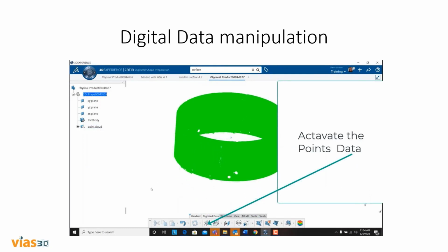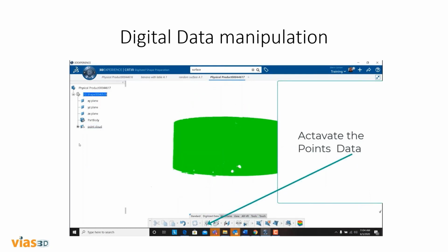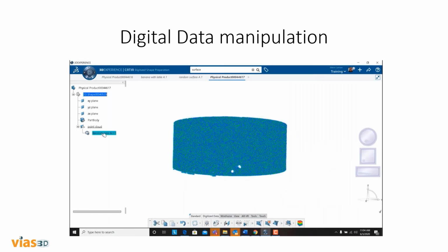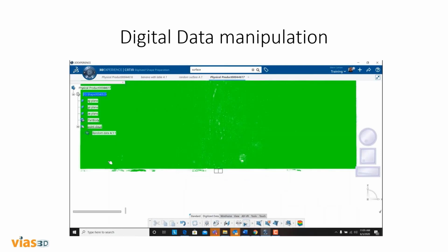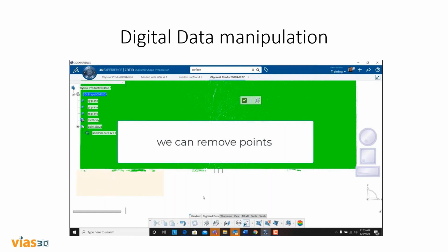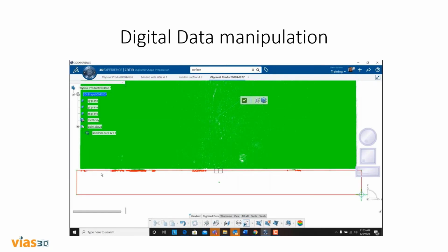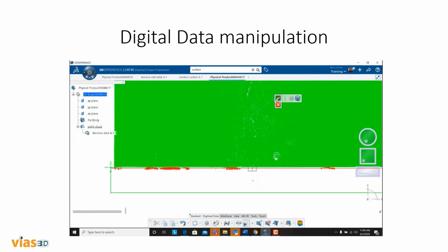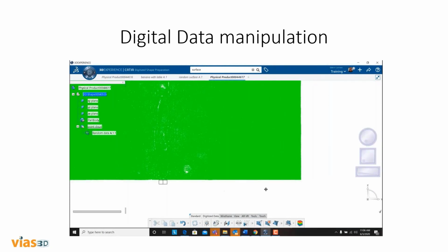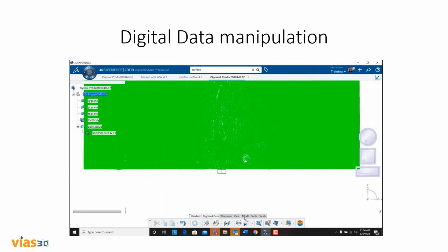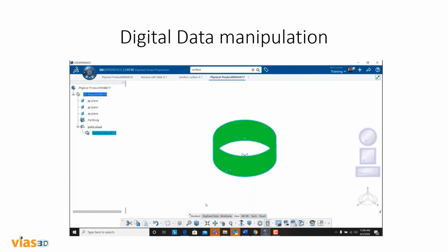So if you look at that, you can actually see the heat deformation in some areas of where this thing's buckled and where they welded it. So I'm going to trim out some erroneous points here because you can do that. Remember, when people scan, anything they reflect off of or hit is going to come back as a laser scan, so you can trim those points out.